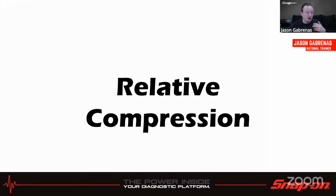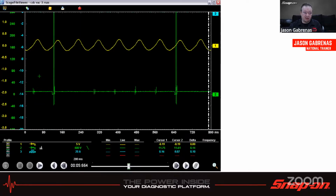Next ones are compression, right? So we have a couple different ways we can check compression. One of them is relative compression. So that'd be relative to each other. As you're cranking over the engine, how are these cylinders matched? In this case, this is a known good vehicle, and we can see it's pretty much the same. What we're doing is checking the cable to the starter and checking how much current the starter is drawing from the battery in order to see how the engine is running.